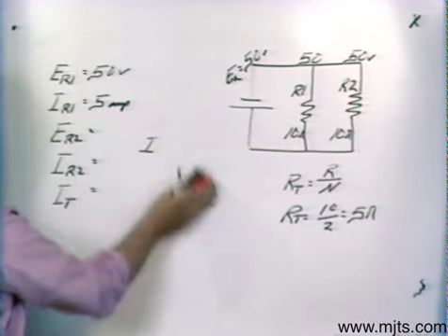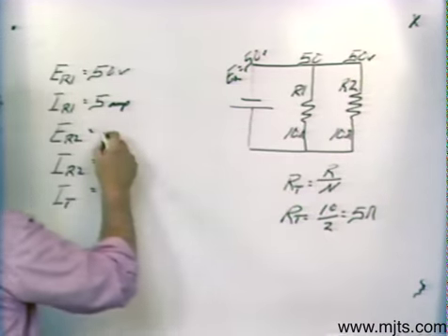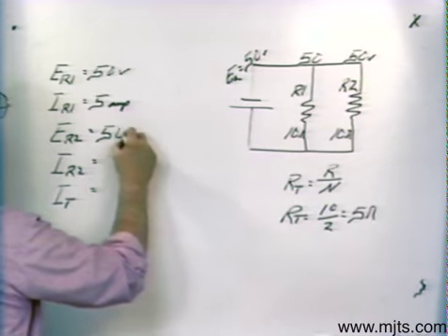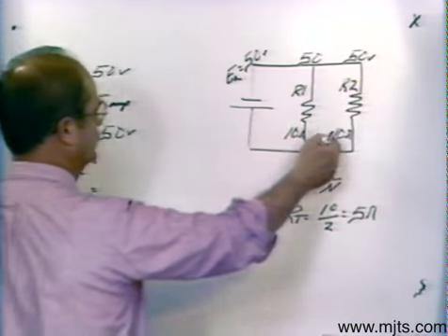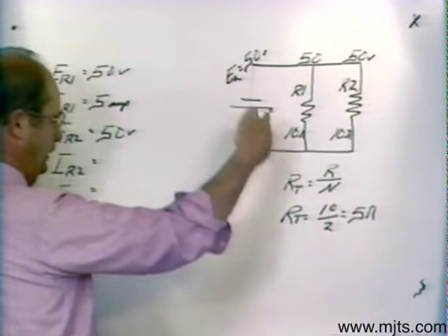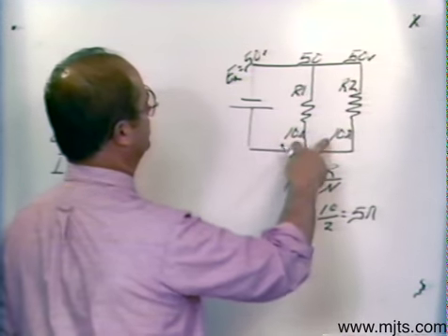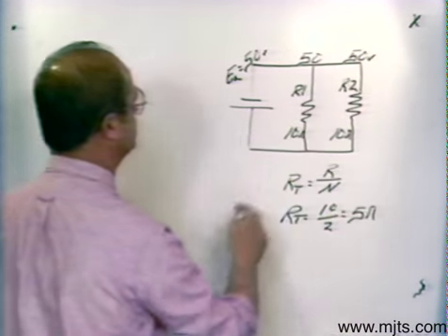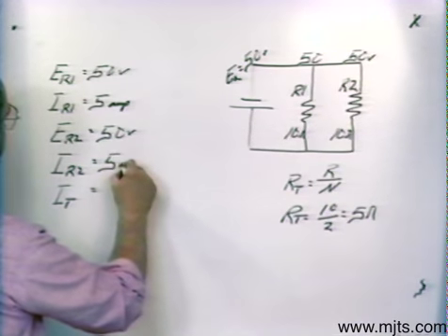Okay. Now voltage across resistor number 2 is also going to be 50. We'll put that up there. The current then, because they're equal, current takes the path of least resistance. Current's going to divide evenly. If I have 10 ohms for both resistors, we know we're also going to have 5 amps there.